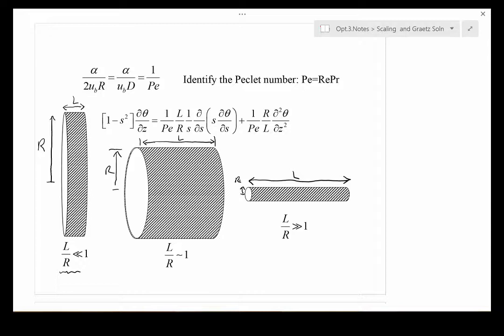So from the perspective of the non-dimensional equation, there are going to be things that strike us. For example, and we just throw this out as a case in point, I'm going to point out that the coefficients of a non-dimensional equation give us an indication of the importance of the physics associated with the term that they modify. So let's write that down.